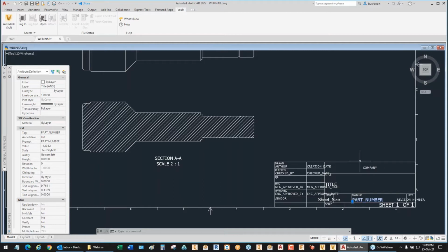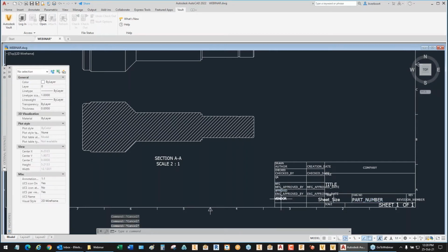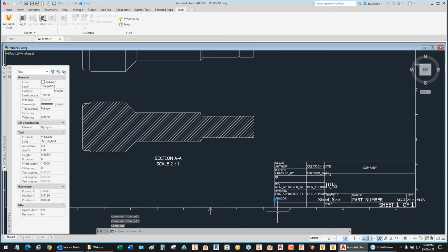They'll just draw lines on an AutoCAD drawing and use those lines as a way to wrangle, gather and collect some text information. So you'll notice here that that's the case. We've got a combination of a few things where I've got just plain text and some attributed blocks. And if you're looking at the properties panel over here, you can see as I highlight the different items, it is a blend of what we've got going on.